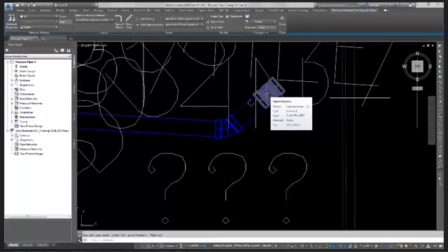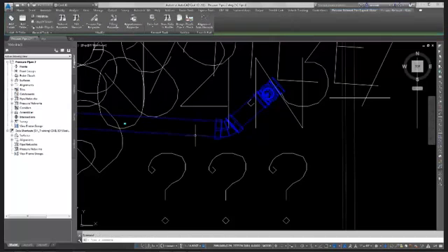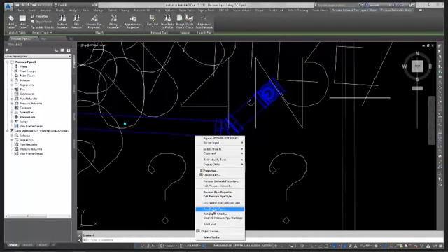You have the ability to do design checks within your pipe network by right click, run design check, and what it'll do is it'll look for open pipes. So if there isn't a gate valve within, I think it's 5 feet. I haven't really measured it out or proved that if the gate valve is more than 30 feet away, that it won't work. But it will look to see if there's a gate valve, if your pipe closes, or maybe I forgot something, so now my ordering or my bill of material is wrong.